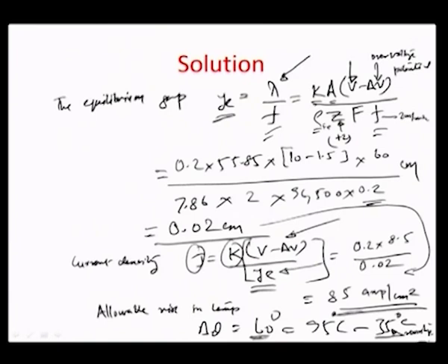So typically if you assume the tool and the workpiece from one side to other, the temperature should actually start from 35 degrees Celsius ambient and go up to 60 degrees more. This is delta theta. Okay. So as the electrolyte is flowing, it should not go above 95 degrees Celsius to give the minimum velocity advantage to the electrolyte. So therefore now we can calculate the design velocity, which is given by square root of J times L by K0 delta theta rho E C E.